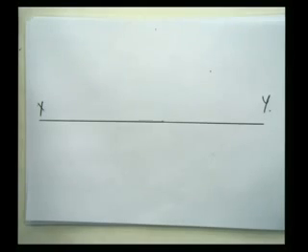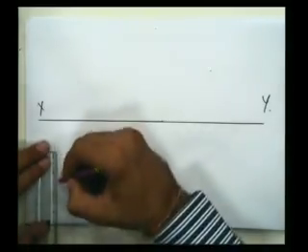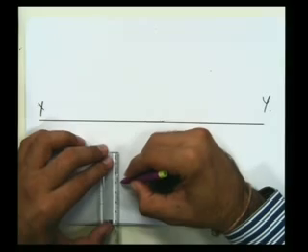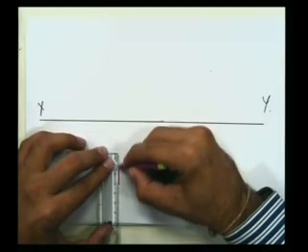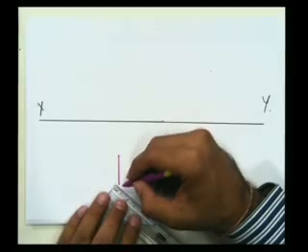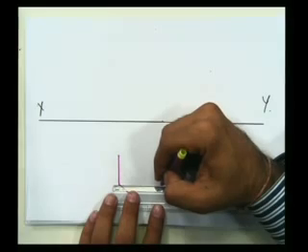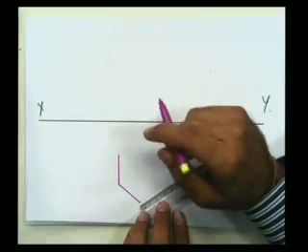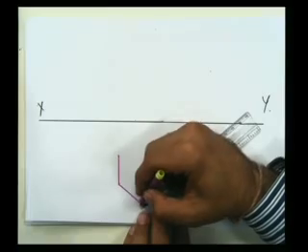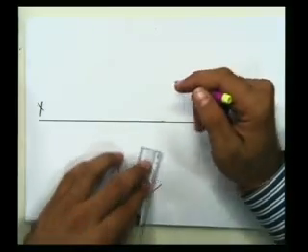which is a sectioned pyramid. In the top view, first of all we will be seeing a hexagon. So first of all I'll draw a hexagon. Now again I am going to use a rough dimension to draw it, and I'll draw it at the center because there is only one figure. 30 mm, 30 mm, 30 mm.